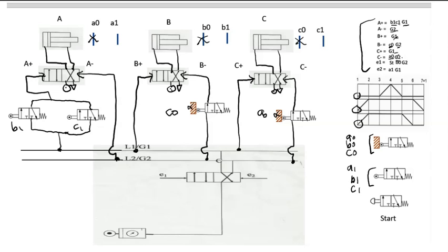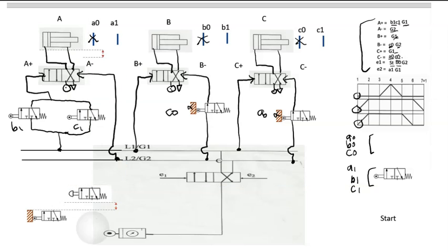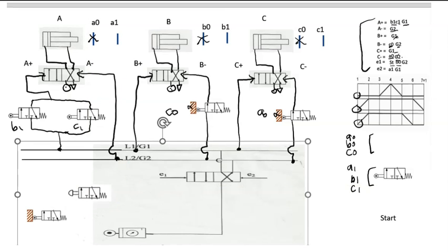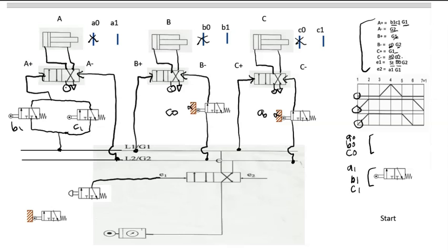Right, now we're going to start with the E. So E1 is going to have start button, ST and B0. So choose the start button. This one I take the B0, and the start button. All right, and then we're going to link it. So remember, start button always use the right side, and B0 we're going to use the left side because it's a touch limit switch. And from B0 we're going to G2. Okay, G2. And now we're going to do the E2, the last one.